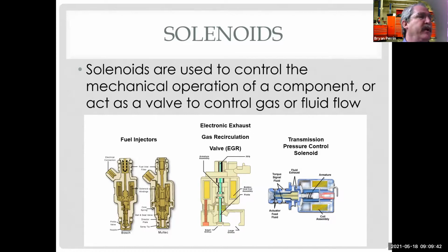It should move. And now in the case of transmission solenoids or EGR solenoids, I can actually watch it jump up and down or move in and out. Injectors, all I can really do is hear them click.